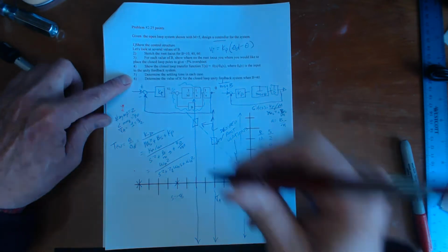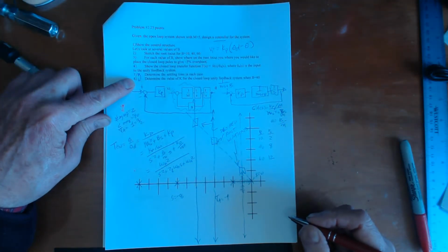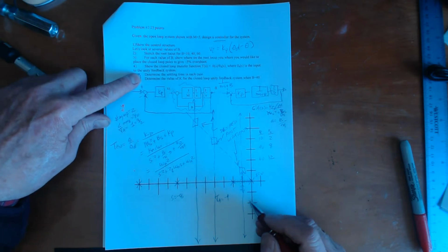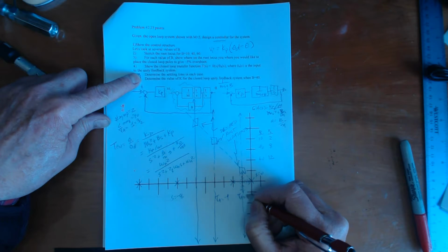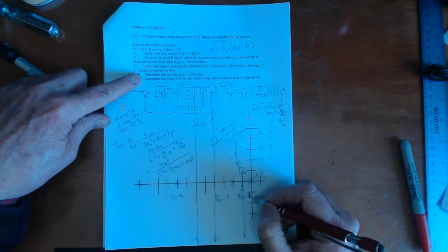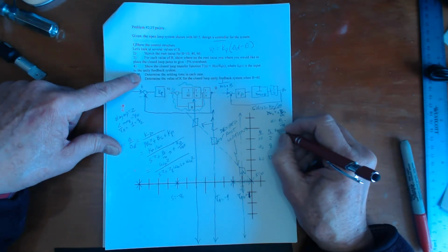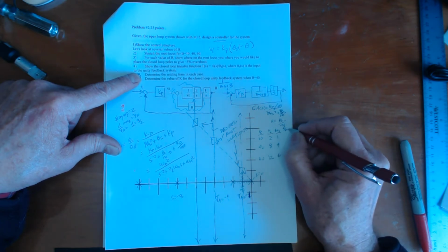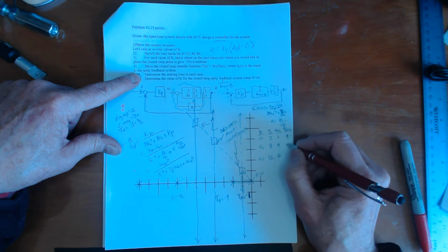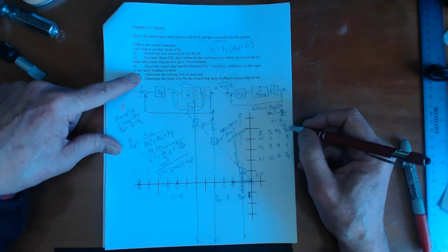Determine the settling time. I realized I kind of swapped these; I should have asked the first one. Determine the value of K for the closed loop unity feedback system when B equals 30. Well, this says determine the settling time in each case. So the settling time happens right here where sigma A is equal to minus 1. And so here's zeta omega n, in this case 1, 4, and 6, and that means 4 over zeta omega n is going to be 4 seconds, 1 second, and 2/3 of a second. So maybe I want to put the settling time here, TS.